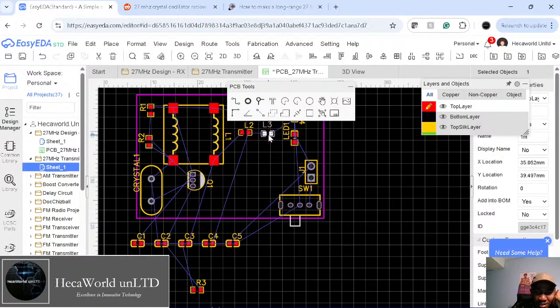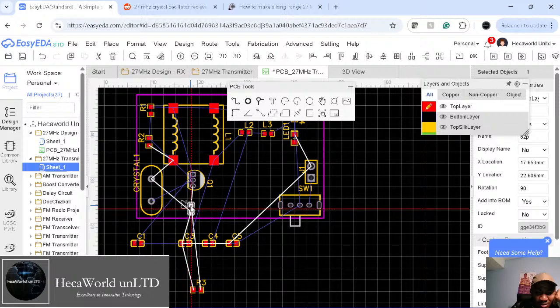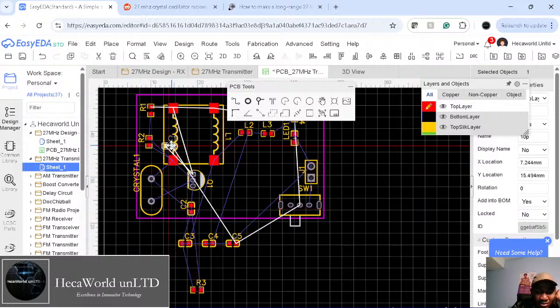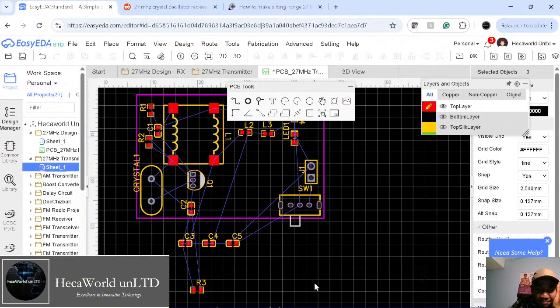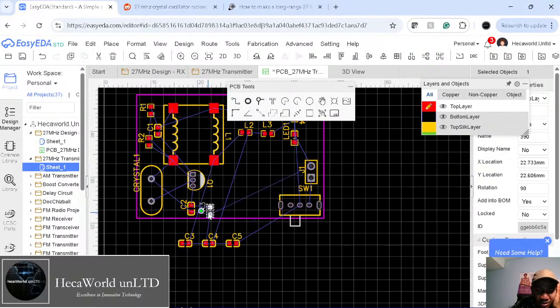So we're gonna drag L3 side by side, and then we're gonna have this capacitor C2. It's right here. C1 is right here. And then R3 is right across this one here. So since they are parallel, I'm going to make sure that they appear that way. And this guy should be oriented this way instead.